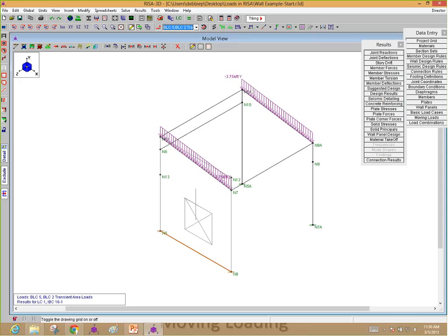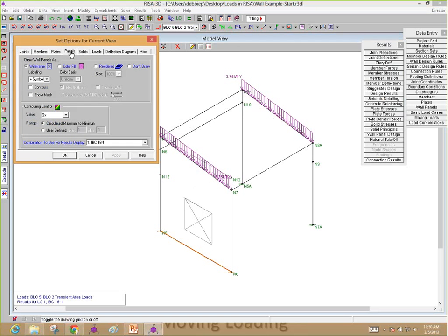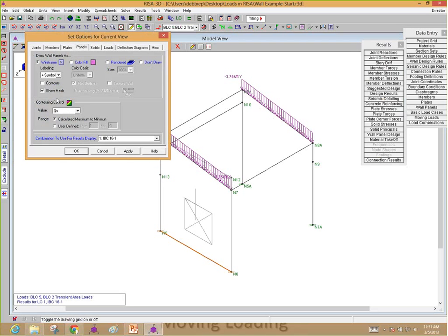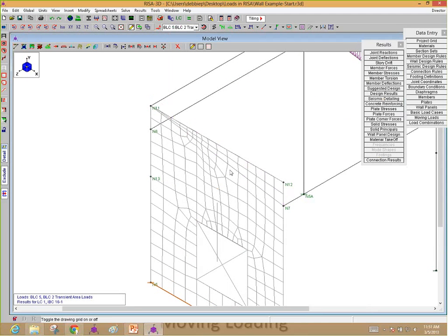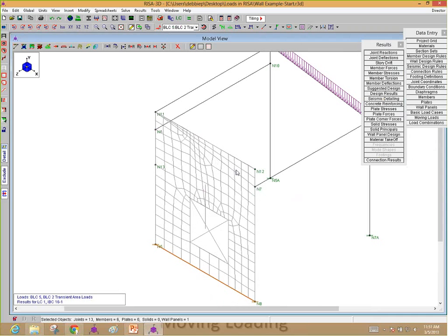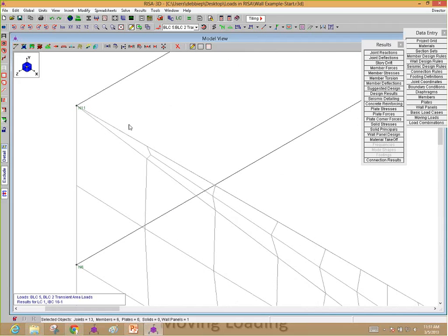We also can see here, let's take a look at how the wall panel meshes. So I'm going to look over to the panel spreadsheet here, our plot options, and I'm going to show the mesh. And I'm just going to see here, but let's turn that off there. There you go. So I'll turn it on and turn it off. Each single location there got meshed to this wall panel, so that distributed load is going right into the plates there. Kind of hard to see it when it's showing, but you can see when I turn it off, just unselect it.